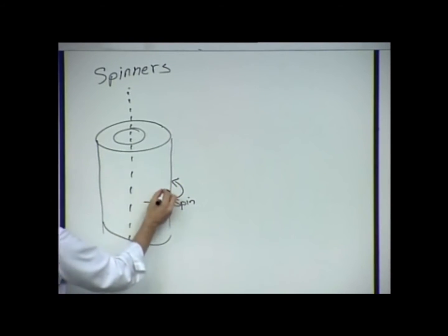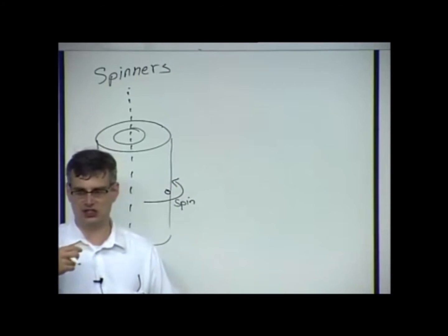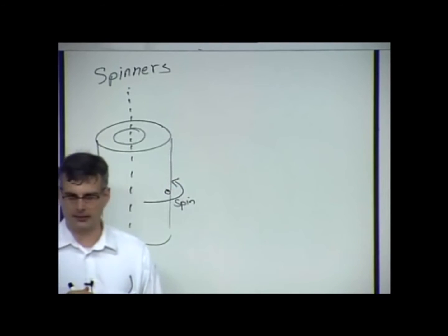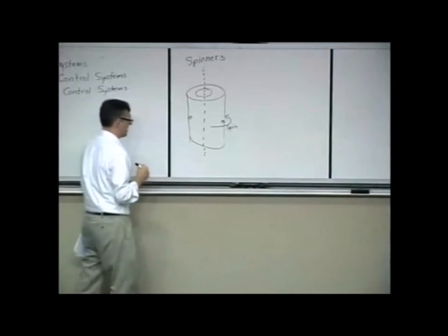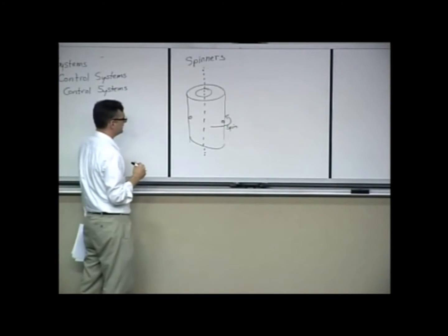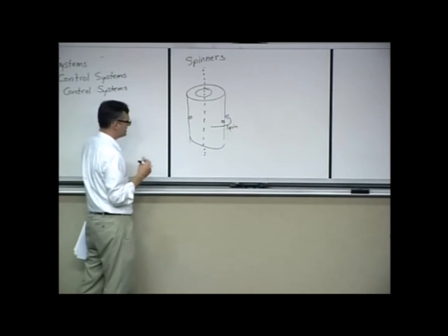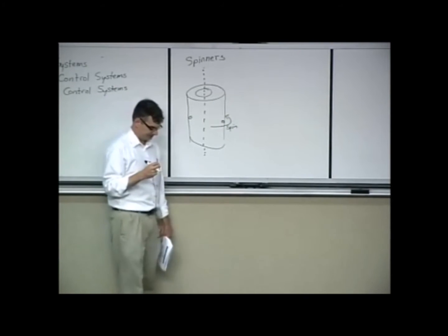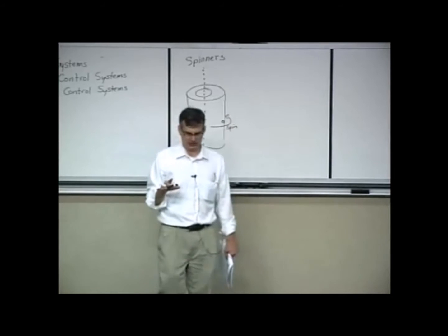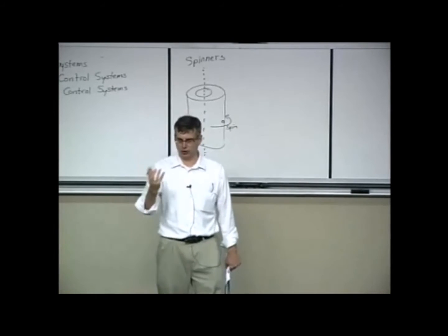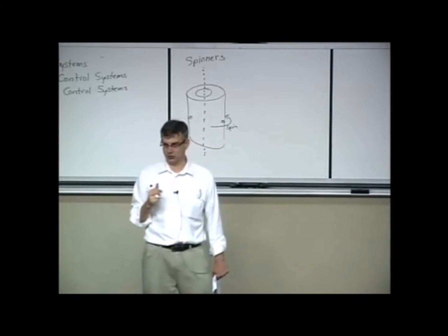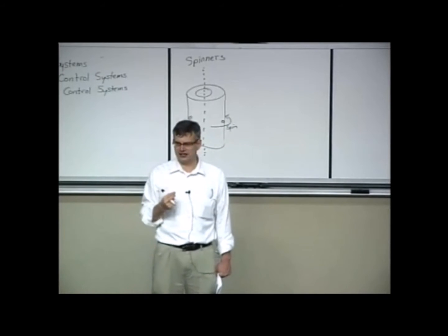It is good to have maybe some little thrusters on the side so that you can energize, spin up, or de-spin, depending on how your spacecraft is performing. And one of the issues here, there are a couple issues. You've greatly simplified the attitude control when you build a drum-shaped satellite like this and spin it in orbit. However, there are a few things that you have to be aware of.